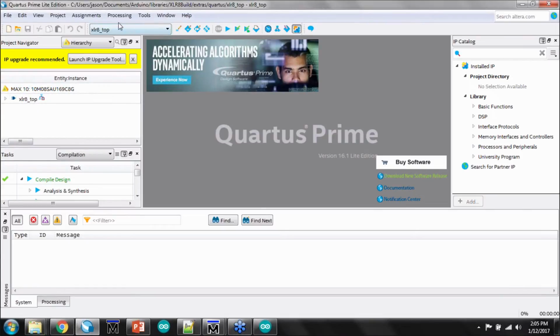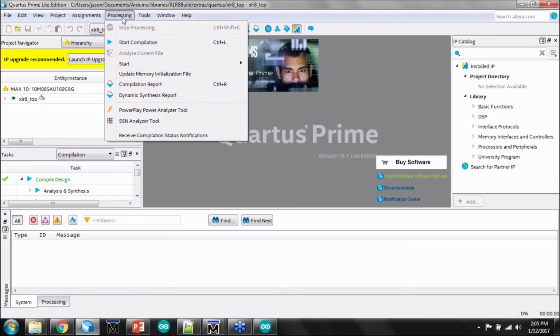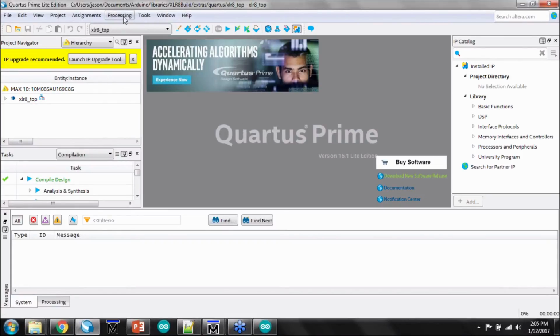Now you can go into Processing and start the compilation. This is going to fully compile the design, everything that we've been working on, all of the LFSR, Accelerate LFSR, and the address packs, and all of our changes will be compiled together. Now I'm not going to go through this step today because it takes a while.